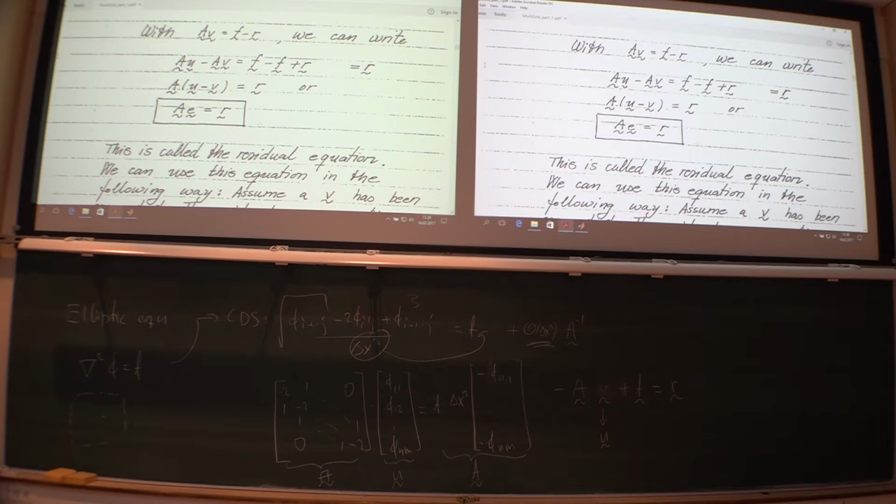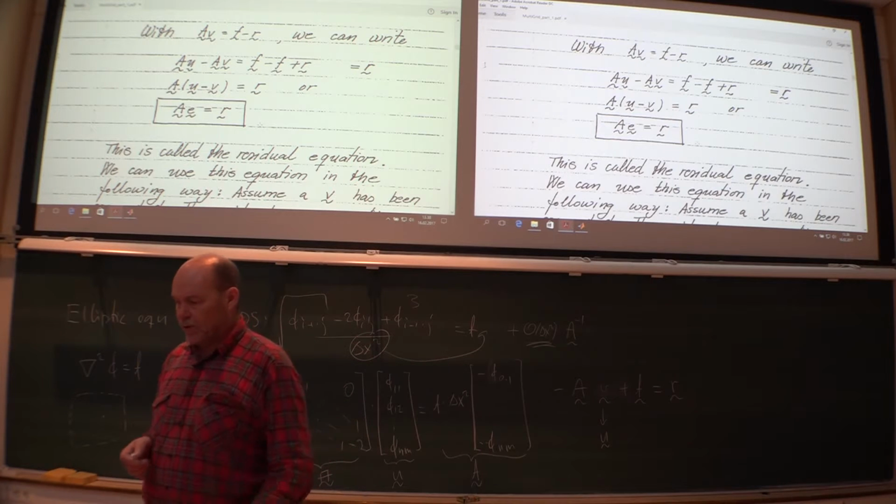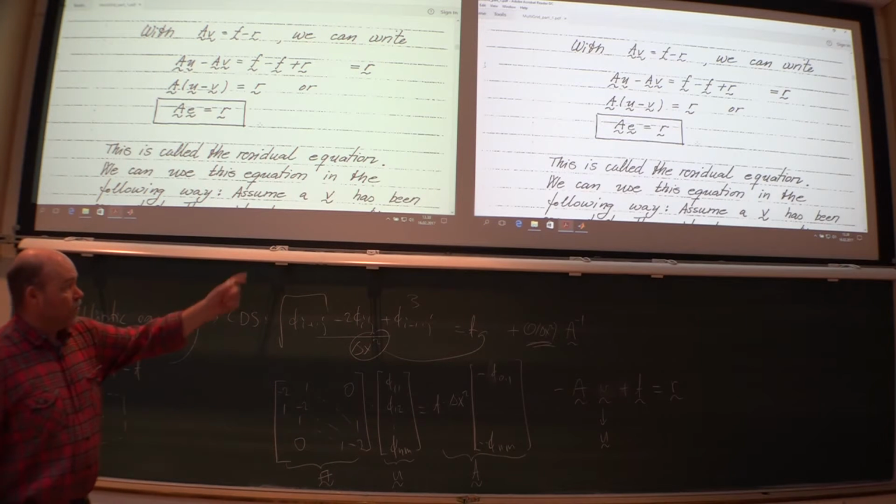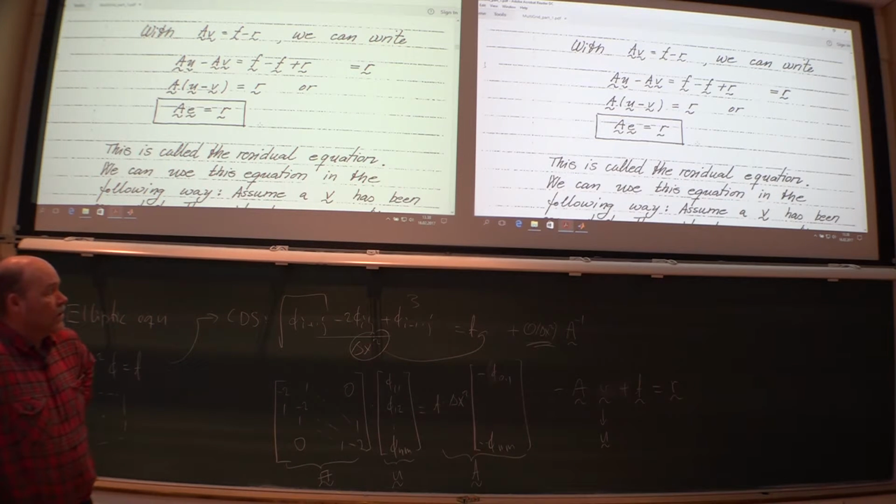And in multigrid, it is actually this residual equation we are now going to focus on. And the reason is actually quite simple. On the fine mesh, of course, you will operate with real quantities. You have a solution for your unknown. So you want this one with dimension, you might say. But on the coarser level, we are going to deal with the residual equation.